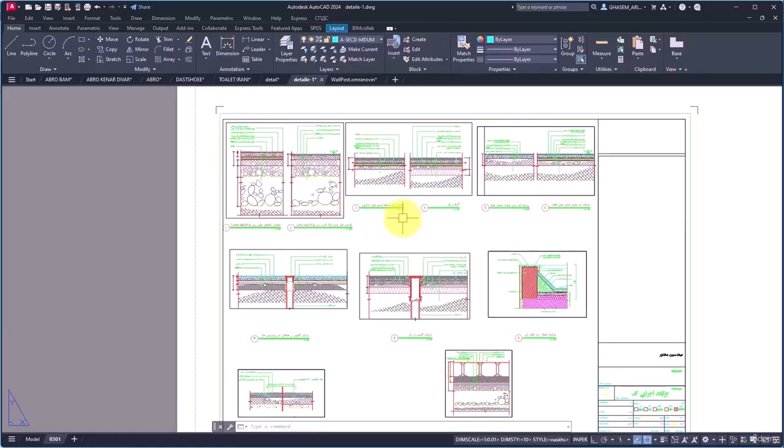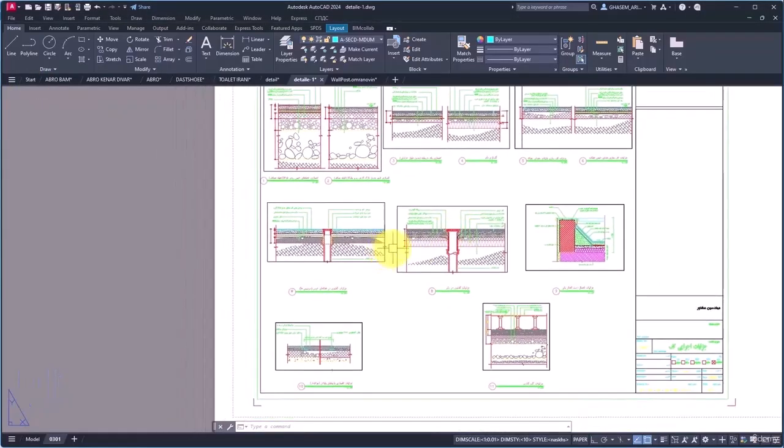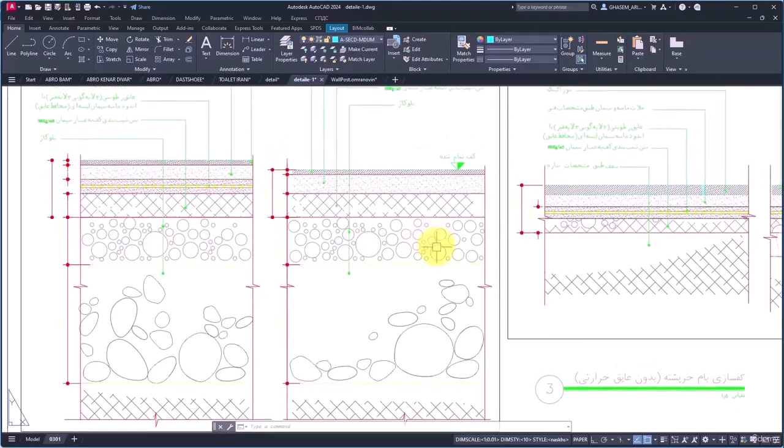You should always try to have LOD structure in your modeling process. And you should probably have LOD 300, 350 or even 400. And 300 or 350 can be enough for most of the projects to have good results. But for shop, you have to have LOD 400. And for sure, the process of having these results with LOD 400 is hard and time consuming. I'm telling you this because you have to manage your time.